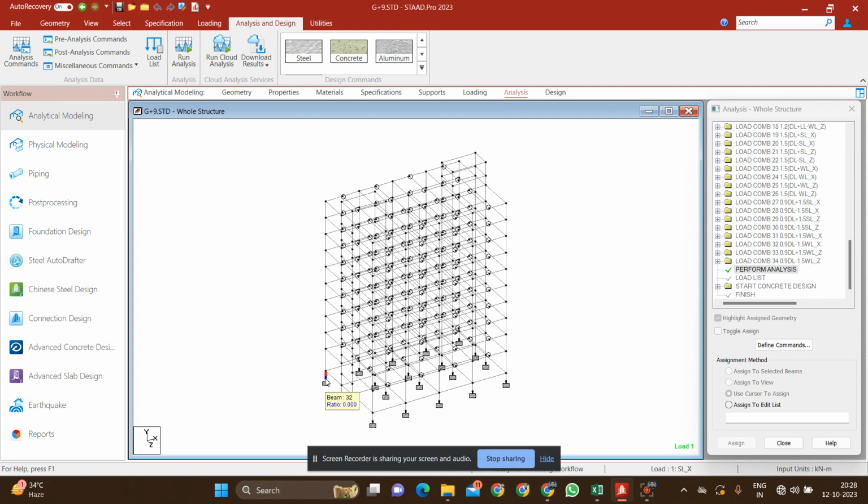So we can do something so that some members will be designed all together, like where the requirement of reinforcement is very close to each other for some members, so we can combine those members and design as per our choice. Like from STAAD we will get the requirement of the steel area and other things. By that we can give our own reinforcement bar and number of bars as per design, as per requirement.